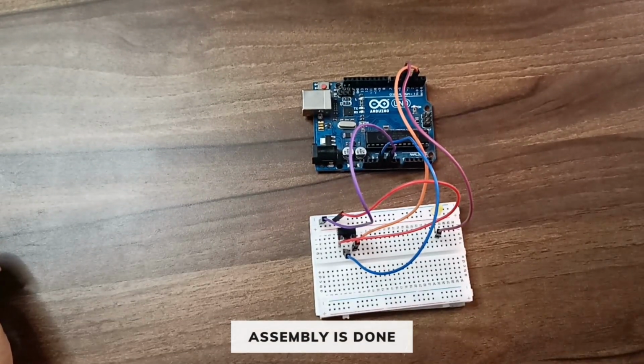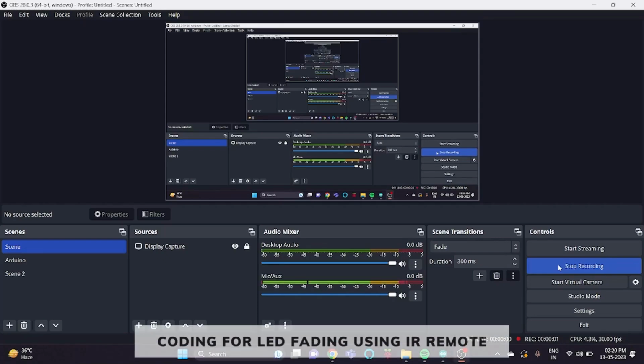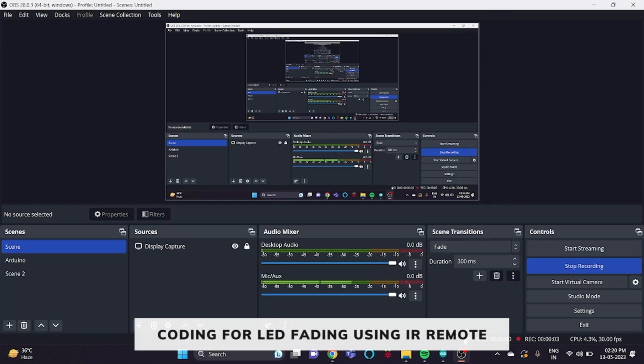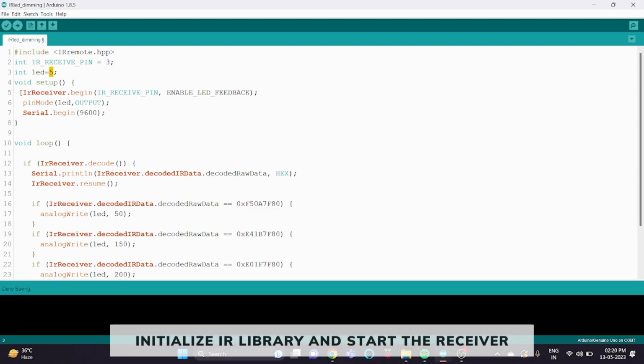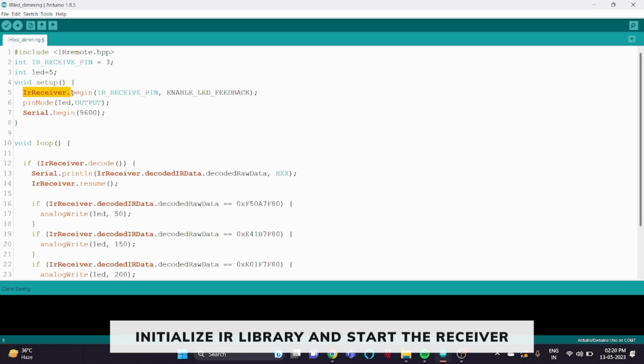Now we will upload the code. Coding for LED fading using IR remote. First of all, open the Arduino IDE. Here, first we have included IRremote.hpp, which is the IR library. Then we have created a variable IR_RECEIVE_PIN for the TSOP output pin and assigned pin 3 to it. Then we have created the variable for the LED and assigned pin 5 to it. In the void setup, we have written IrReceiver.begin(IR_RECEIVE_PIN, ENABLE_LED_FEEDBACK). This will start the receiver.